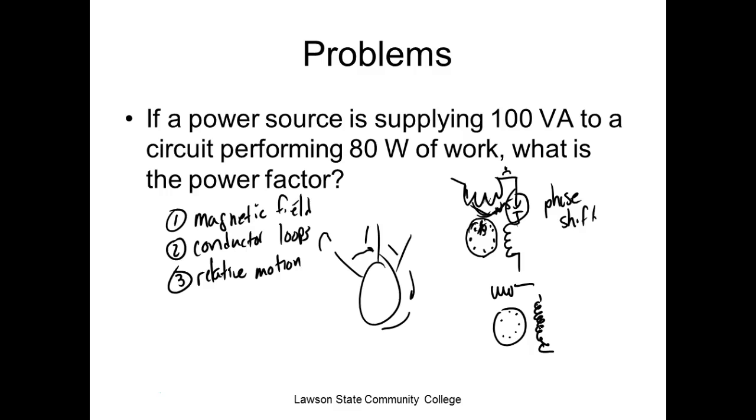And we have some they call capacitive run motors, but actually it's just got another capacitor that they leave in the start winding all the time. And it creates more torque, more run torque for a smaller size.